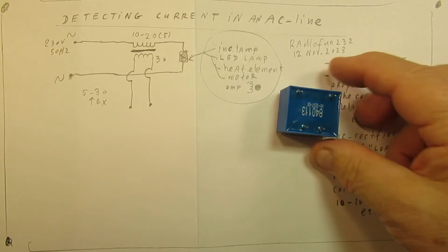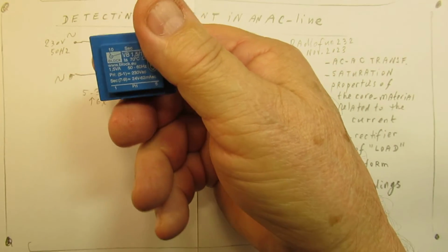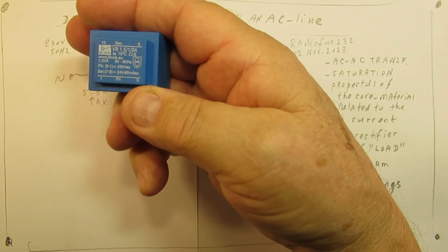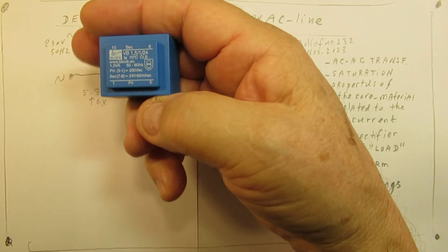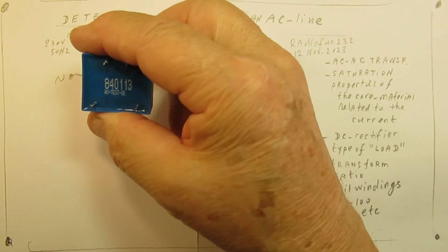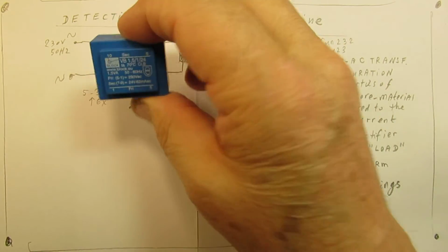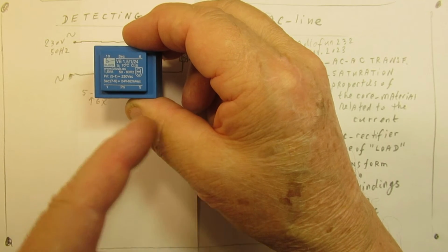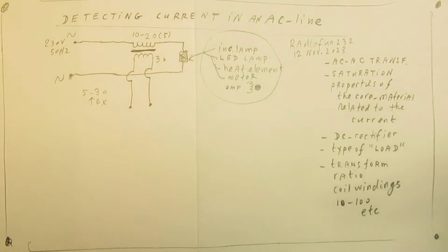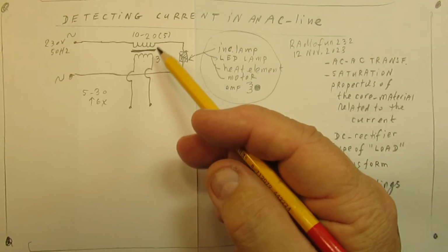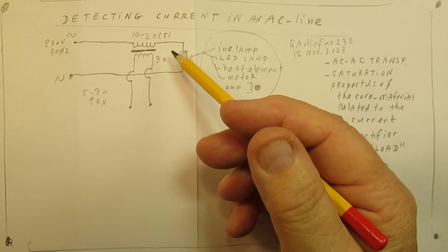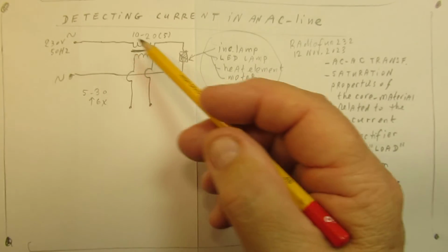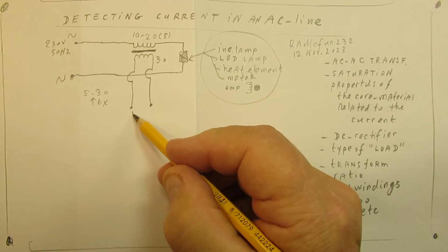It has also to do with the properties of the core. I cannot get too much in detail. It's hobby. But when you study the more serious electronics books, etc., there's a very important thing, and it is the saturation of the coil. When the maximum current flows here, in this part, and the coil gets saturated, there is no longer a relation between the current that flows here and the output voltage that we see here.